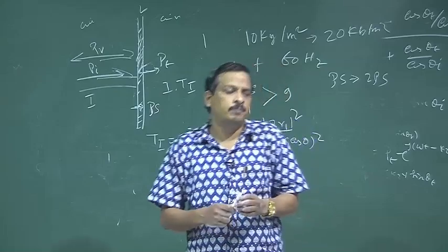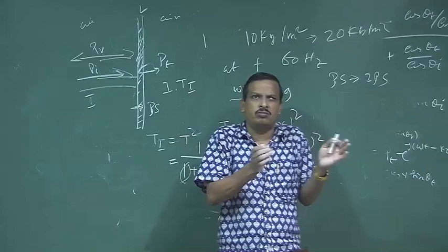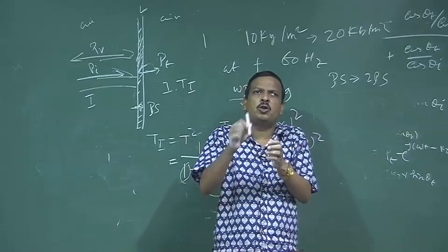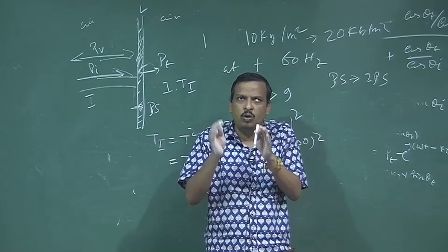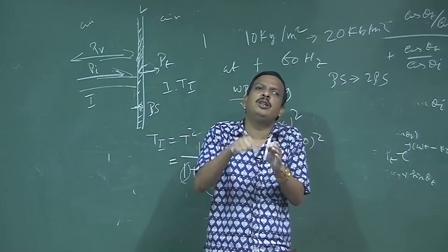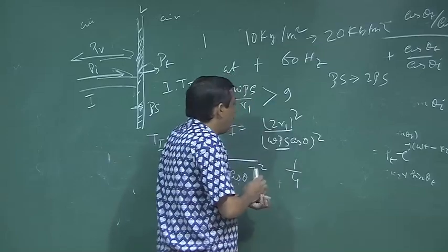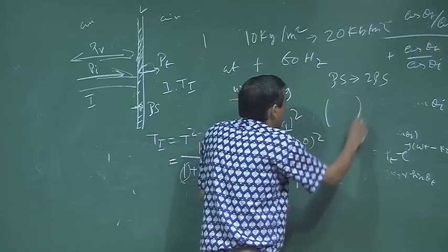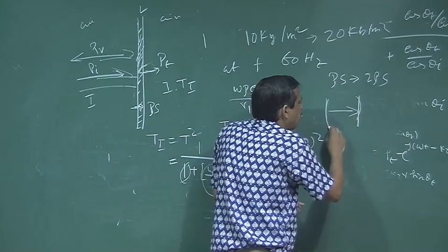Sometimes in acoustic isolation, when we make a door, instead of a solid door, we make a glass door with two glass layers, and in between there will be air. So, the transmission will be reduced. This is the studio, and this is the glass door in one layer. So, the mass law calculation applies.